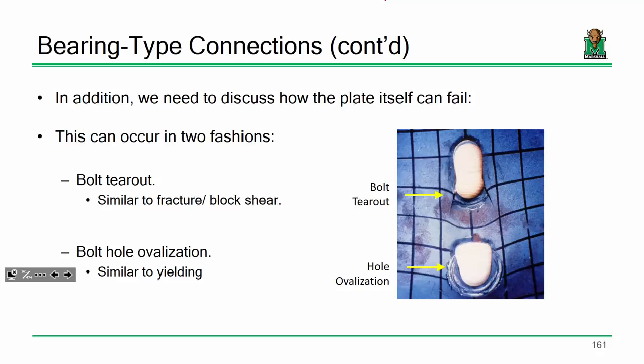Now, like I said, one of two things can happen. See right here, the bolt kind of mashed into the plate, and the plate almost turned into a little bit of Play-Doh right there, and experienced that permanent yielding. This phenomenon right here, we call that ovalization. It just mashes in and stretches out the hole a little bit. Now that's one particular way that the plate can fail.